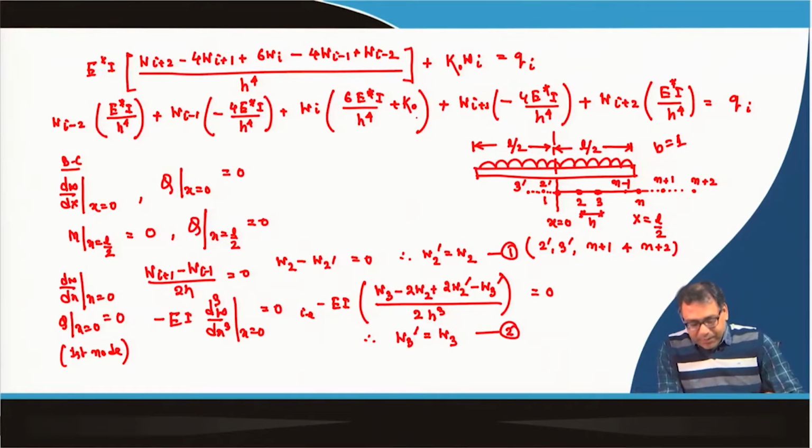So, now you apply these basic equations in finite difference form at all the nodes from the first node to the nth node, and at some nodes, basically these 4 nodes, imaginary nodes will come. Those imaginary nodes you replace with real nodes.